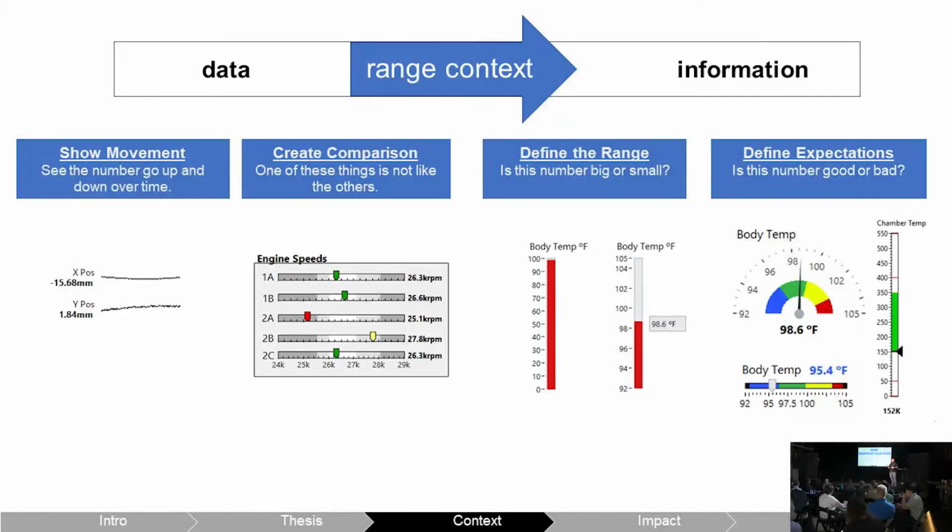And so sometimes just that little bit of context of like, oh, I can see 4 of my channels are flat, or, let's say I have a bunch of thermocouples and I can see that a bunch of them are reading interesting and one of them is flatlined. Now I know where to go start poking around.